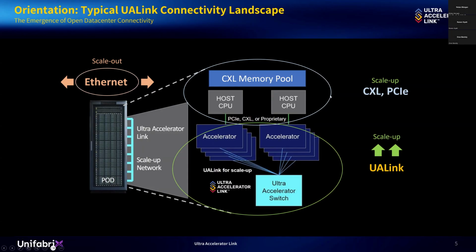The host side here with CXL could also be considered part of a scale-up semantics, but it goes into a different protocol domain. There are other protocols involved in the AI cluster world and ecosystem. Some of them are very well known, such as NVLink from the NVIDIA world, and other attempts to take Ethernet or Ethernet physical layers and use them for the scale-up domain.